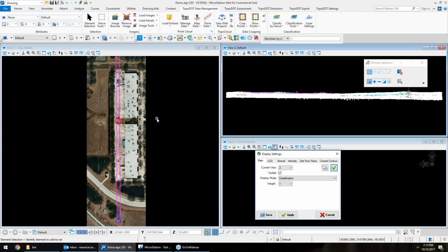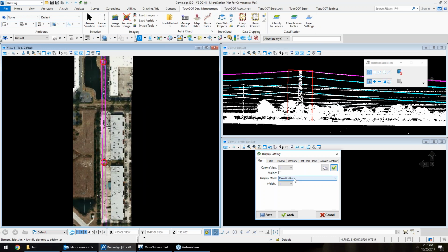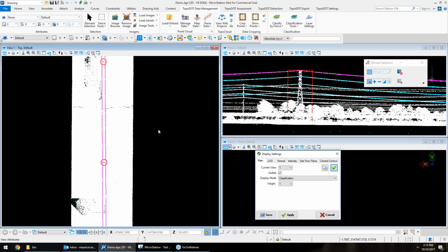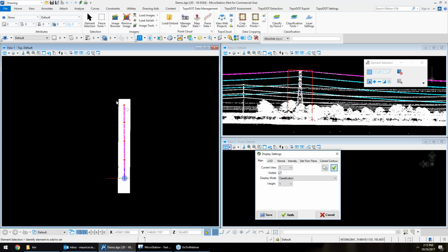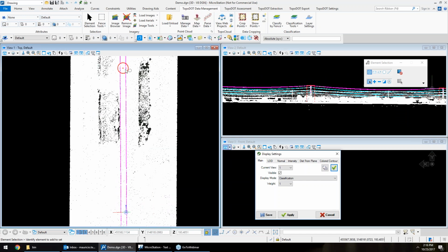All right, guys. So Ted talked about a lot of the tools there. We're gonna go ahead and start off with the encroachment clearance tool here. So we've got a bunch of data loaded. This is of the power line data, actually behind our office. So I'm gonna go through a little bit of the tools that we already have available and we've had for years now. And the reason why is because you need to run those first before you use this encroachment clearance tool. So in this case, I've already extracted some of the power lines and the towers.